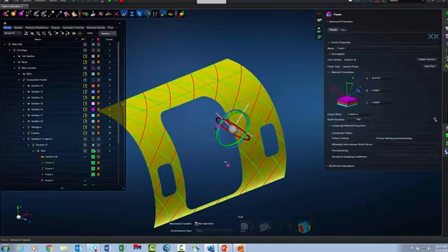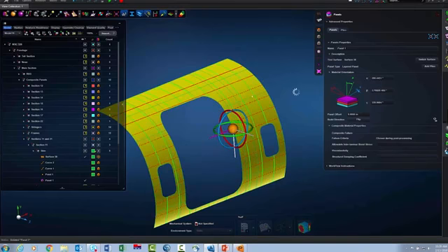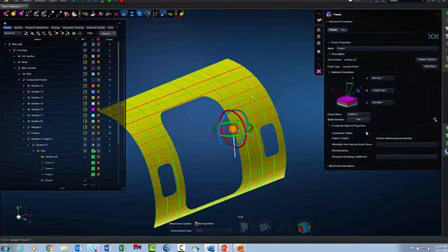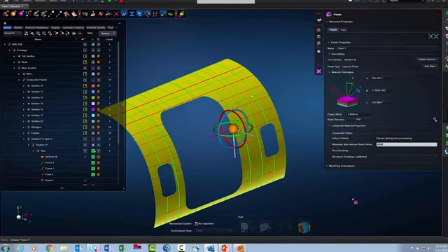I know I get a lot of questions about orienting with respect to the geometry itself. It's very easy to use this little coordinate system to select an edge on the geometry, or some other feature of the geometry, to orient with that. So I'm going to go back to the global X by orienting with an edge of the geometry. Okay, so let's go ahead and enter an interlaminar bond stress for the Nastran composite components. That's the SB parameter on the PCOMP card.